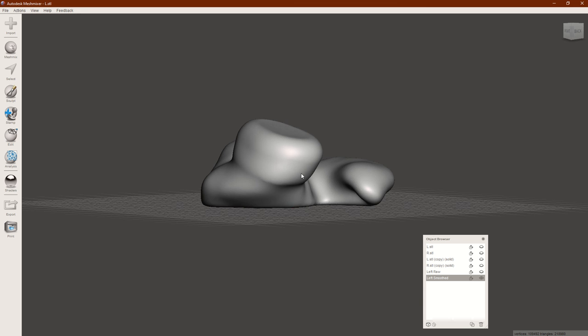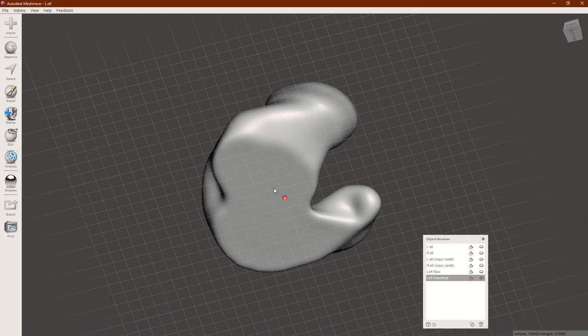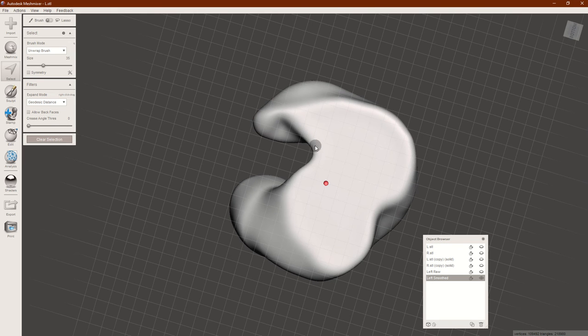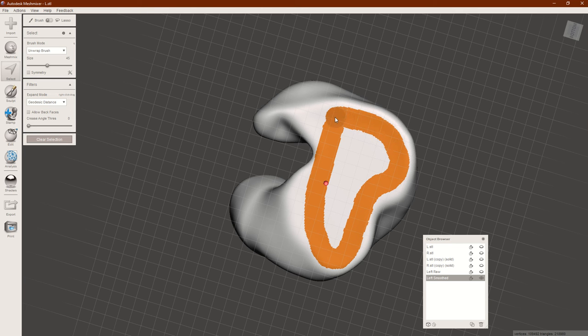Okay, so now that we have this nice earpiece, the part that's not in the ear is the next part we have to focus on. So doing that, I need to extrude this cap area. I'm going to do it about 14 millimeters in total. So to do that, I like to basically take something that looks similar to really the African continent is the thing that comes to mind, and I'll show you what I mean. I'd like to do a flat-ish straight part here, and I like to move down to the bottom, and you can add and remove a bunch of this.